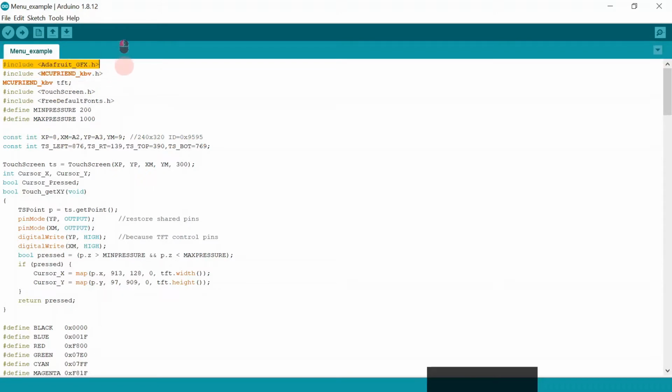So it is based on the MCUFRIEND library, which is based on the Adafruit. But the MCUFRIEND library has all the serial communication that happens at the beginning of the connection between the driver of the LCD screen and the Arduino. So it's kind of a driver library for small touchscreen monitors like Adafruit 320 pixels or 280 pixels, 240, 380, and so on.